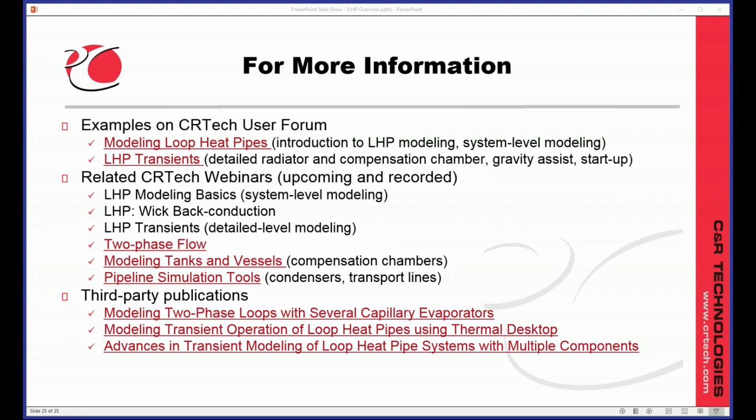So first question on working fluids. Yes, in general, they do use the same working fluids as heat pipes. For example, ammonia is used in both of them. I don't know that there's too many cryo heat pipes, but a cryo CPL or LHP would use something that you might not traditionally think of, like nitrogen or xenon or neon. I think the main difference on an LHP is because it has a significant subcooling, which is not typical in a heat pipe, and because the pressure losses are just not the same as in a heat pipe, they can get away with fluids that you may not want to use in a regular heat pipe.